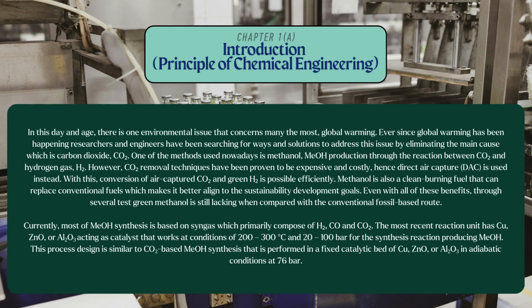Most methanol systems use copper, zinc oxide, and aluminum oxide catalysts at 200 to 300 degrees Celsius and 20 to 100 bars, similar to the carbon dioxide-based process at about 76 bars.